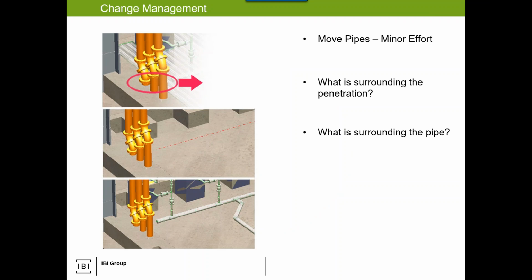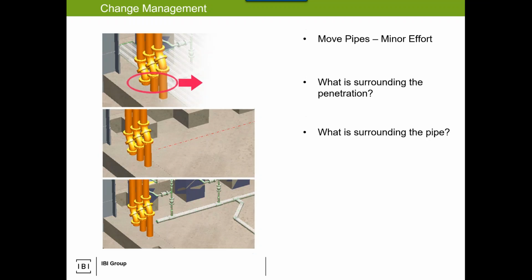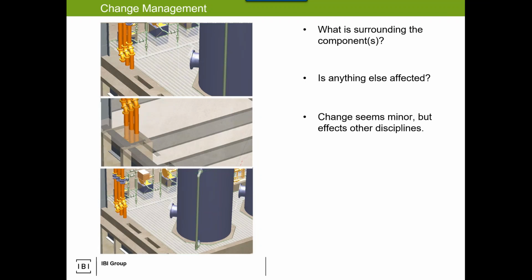And then we can start to help them visualize the impact of the change, the impact of what's surrounding. Maybe as a piping designer, I might say, well, I'll just shift the pipes. It's nice and easy. But as a BIM coordinator, we'll say, hey, if you move the pipes, look at everything around. Here's all the models together in Navisworks that may impact the design decision and avoid clashes and make it more of a quality decision for down the road. So very powerful. You can see the difference there of just moving the pipes if I'm looking at structure versus, hey, I've pulled everything together. If you move the pipes, you might have an interference relative to the outfall of this tank. Maybe this is a reserved clear space, therefore the pipes can't move into here, and the dialogue ensues. Very powerful, very influential as well.